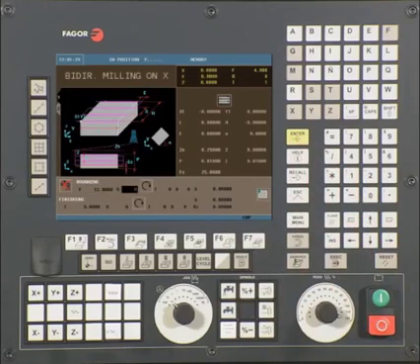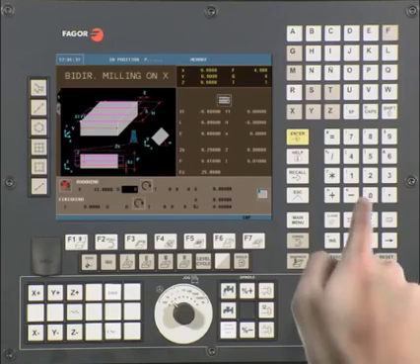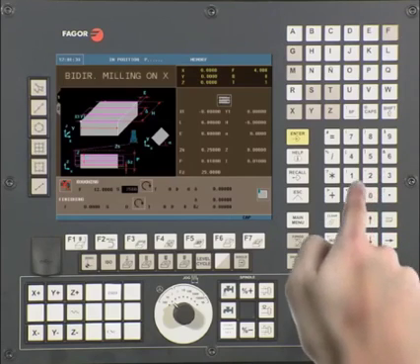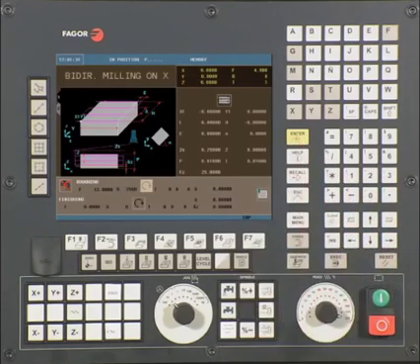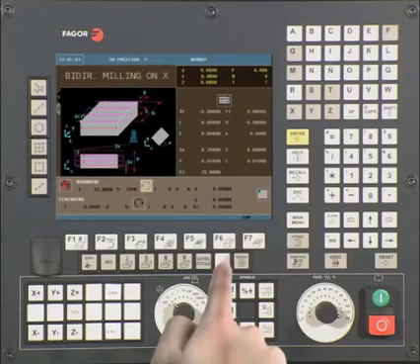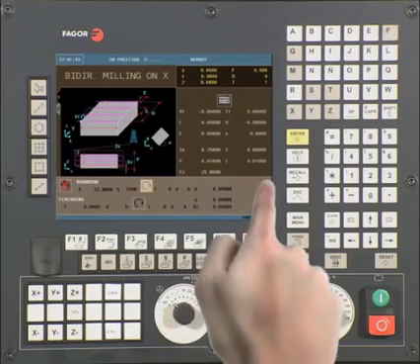S. This is your spindle speed. In this example, we are using a value of 2500 RPM. Type 2500, press Enter to continue. Using the half key, select if you want spindle turning clockwise or counterclockwise. For this example, we will select clockwise. Press Enter to continue.